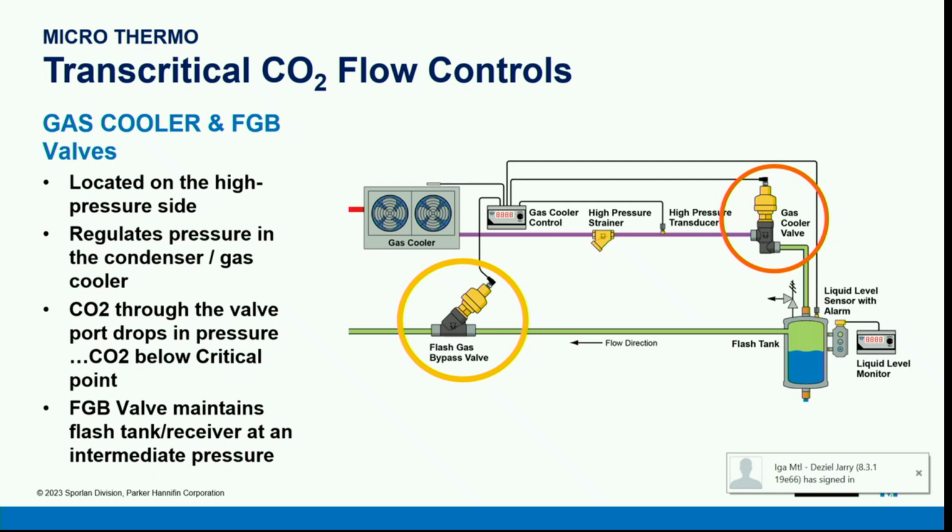The high pressure valve? Okay, yeah, I call it the gas cooler valve, but in the trade they're calling it HPV, okay? What we're doing there, when it's transcritical, I don't care if my gas cooler had 100 fans on it. We're not going to get that supercritical CO2 back to liquid CO2. We've got to get it to change phase. We've got to get it to condense.